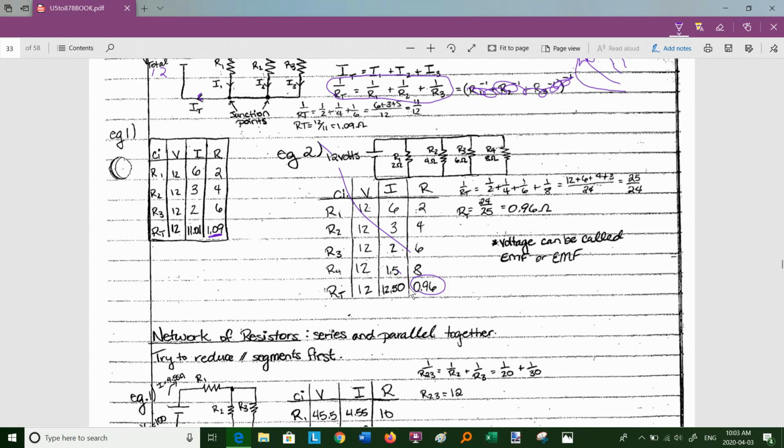And there's only so much current you can draw from your power supply before you get overheating effects and dangerous stuff happens. So your circuit breaker gets tripped if you plug in too many appliances. So you want to be careful on that, and especially, I was just looking at this the other day because my basement is freezing. These portable heaters, don't put them on with any other appliance.